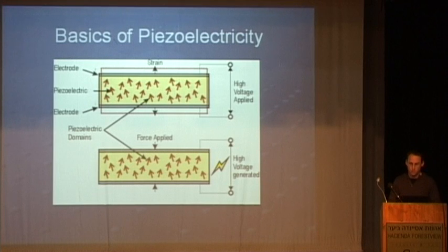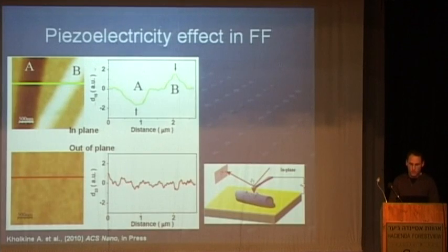on regular AFM. On the right side of the slide is our technique, how we measure piezoelectricity with PFM. We apply voltage to the tip in contact mode, and by applying the voltage, I also create an electric field. I can follow the piezoelectricity of the sample. I can follow two ways of motion.